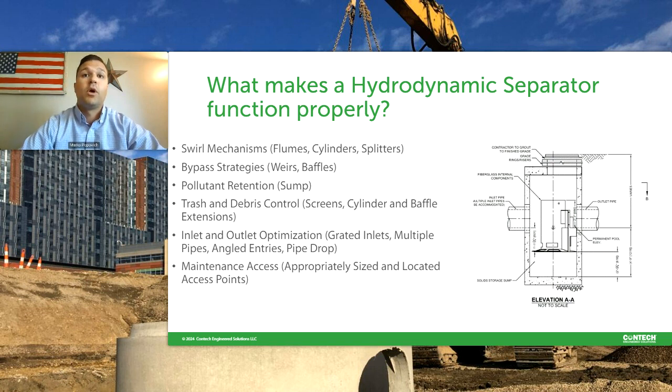Equally important for pollutant retention would be the sump. When we design these, when we test these, the big thing with any sort of pollutant retention is going to be that outlet invert all the way down to the bottom of the structure. As you continue to accumulate sediment there, you could see turbulent forces with larger storm events and even some of the smaller ones. So the key there is ensuring that sump depth is accurate and you're not resuspending everything from those previously captured storm events.